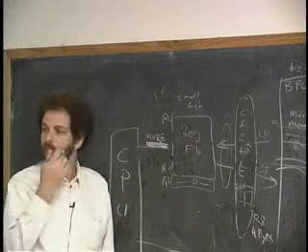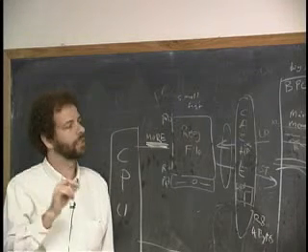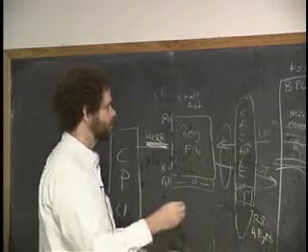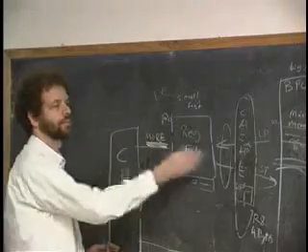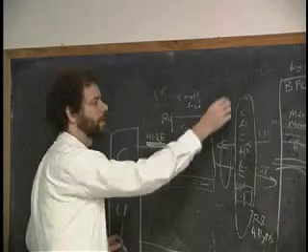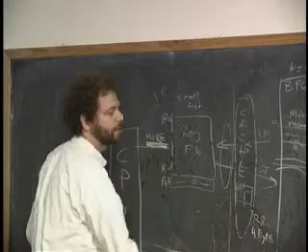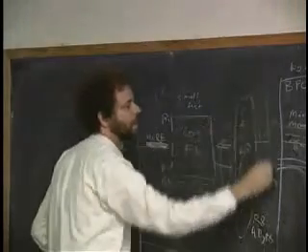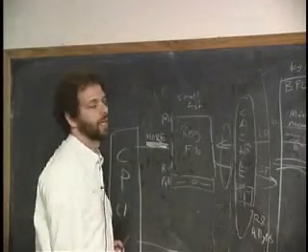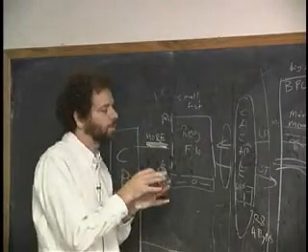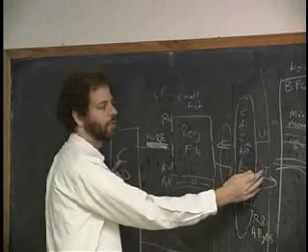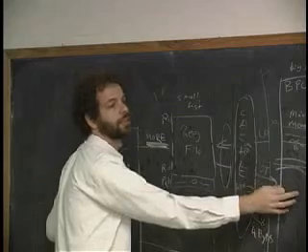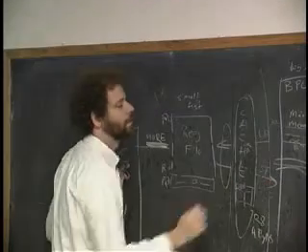Okay. What's the ratio? Sorry. Well, the last thing that I was going to say is that typically the boundary of the integrated circuit, so the processor is on an integrated circuit, the register files are on the same chip, and then either the L1 cache is on the same chip and the L2 cache is not, or for newest chips, both of them are, and the boundary of the chip is there. And it turns out that physically, as soon as you get off of the chip, the one chip that's going to hold all this stuff, and go to a set of wires to another chip, everything slows down a great deal, because you need to drive those wires.